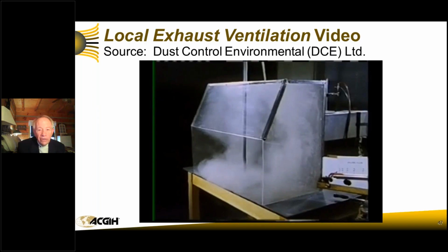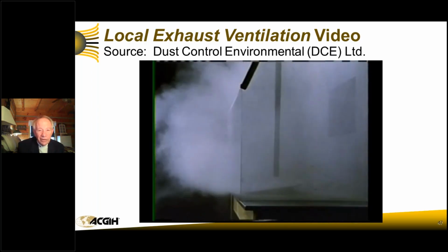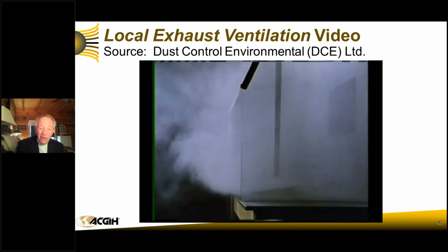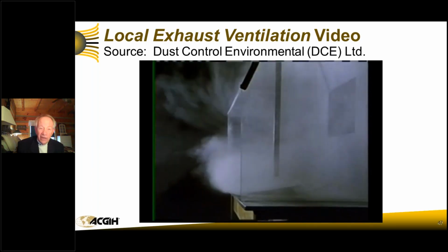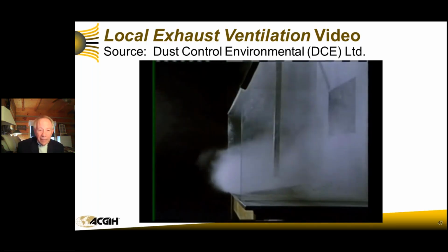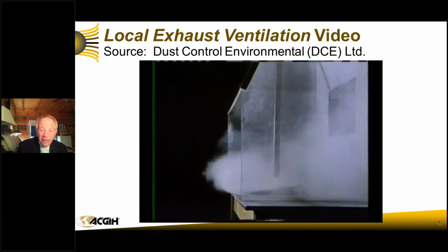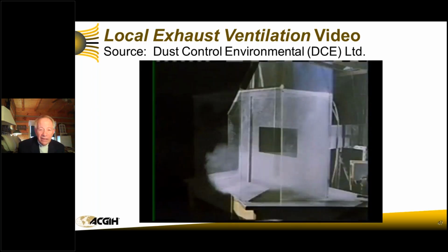In this enclosed hood, we are 100% captured. Well, we're going to adjust it to where it is 100% captured. We'll open up a little, there we go. Now we've got 100% capture. By the way, smoke is a very wonderful way to use it. And that was 400 CFM getting 100% of that contaminant.